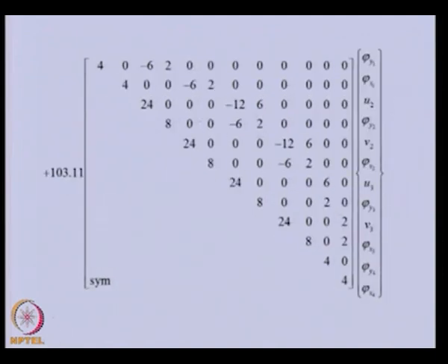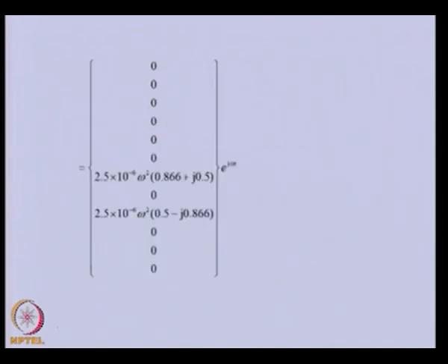So, this is the reduced form of the stiffness matrix, and the reaction unknowns we need to eliminate. Only the terms containing the unbalanced force will be there in the right hand side, but other reaction forces and moments, if they are appearing like at node 1 and 4, shear force will be 0. So, corresponding rows and columns are eliminated. So, only known unbalanced force are here.